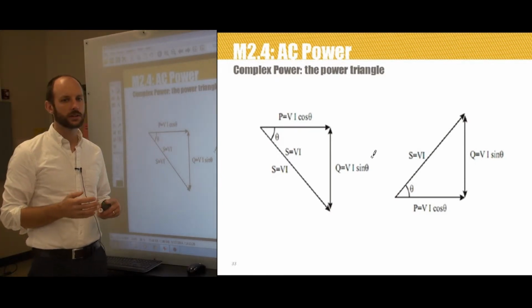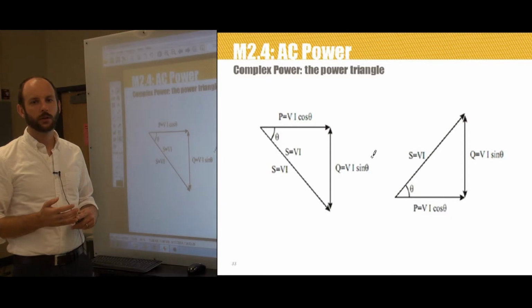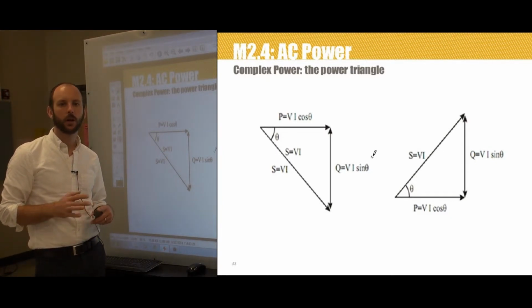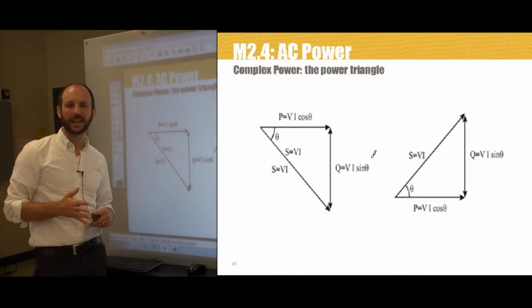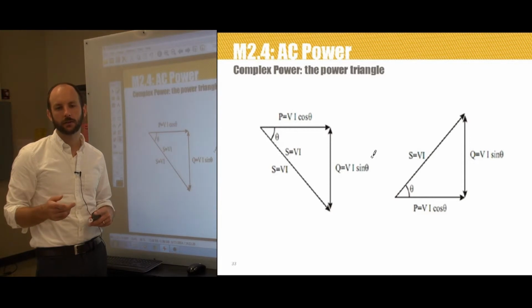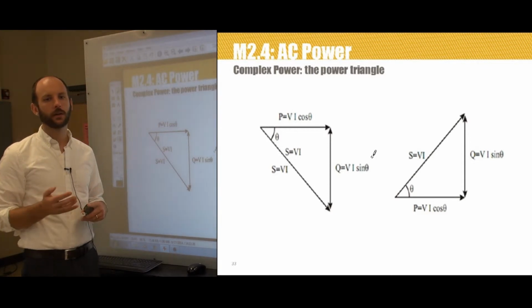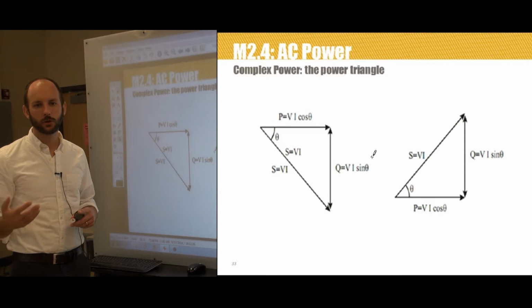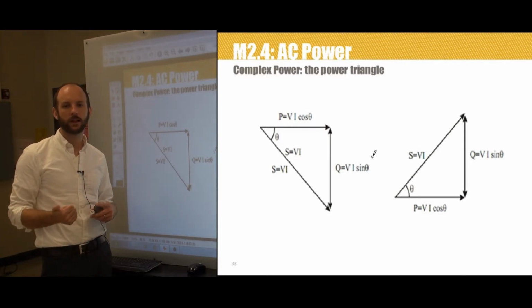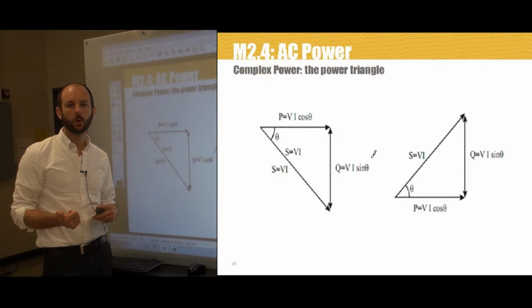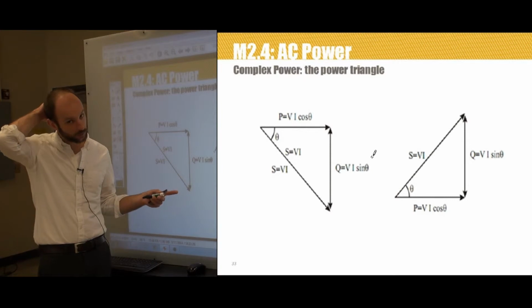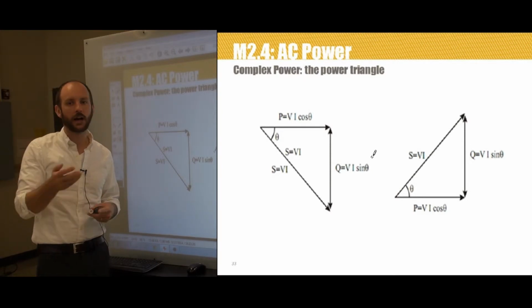Overall, electric utilities have to engineer systems such that the generator is connected to a system with a power factor between 1 and 0.8 lagging to supply, meaning that the system looks inductive. To supply the needed VARs to the system, utilities will often put capacitors on the system to balance out L, or they'll adjust the AC generator's field voltage, which has the effect, which we'll learn about later, of supplying reactive